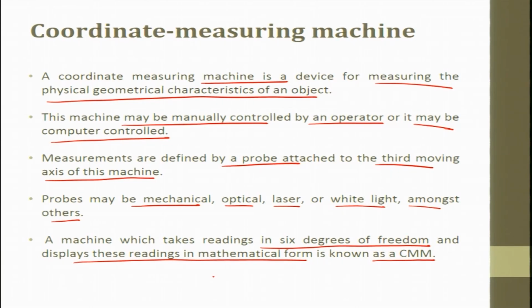If we know that there is a structured form, we can select it beforehand, that okay, this is a circle that we are going to measure. For a circle, 3 points are the minimum required to measure. For a plane, 3 points are required to define a plane. For a cylinder, 8 points are required. For a cone, 8 points are required. I will come to them when I actually show you the lab demonstration.